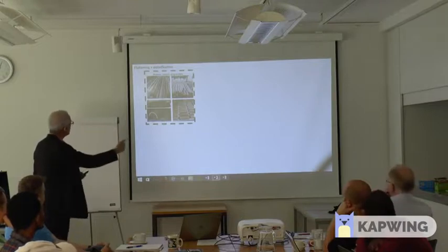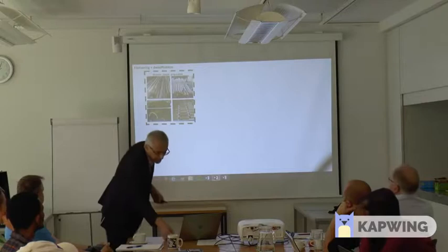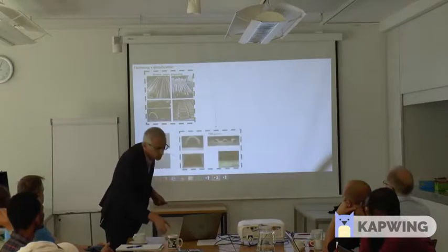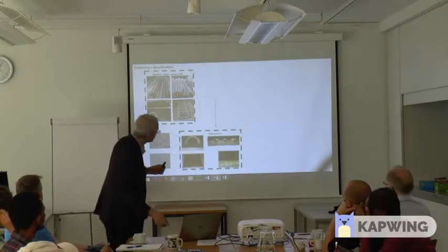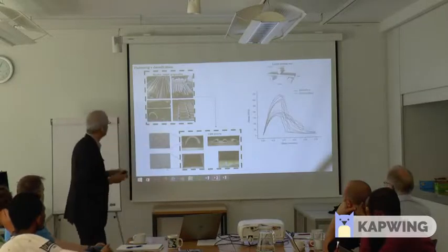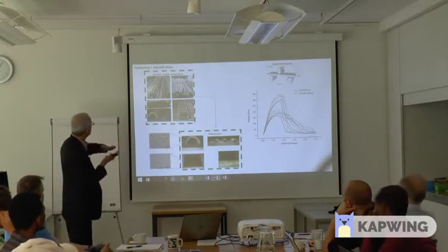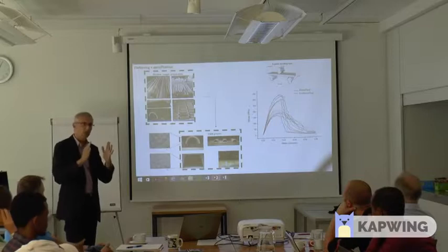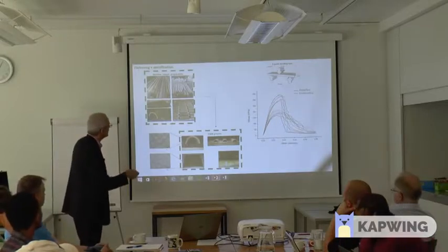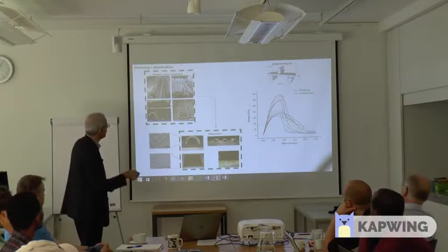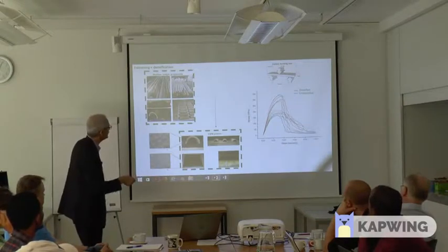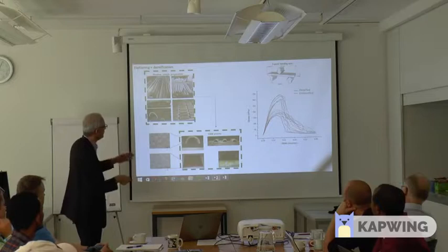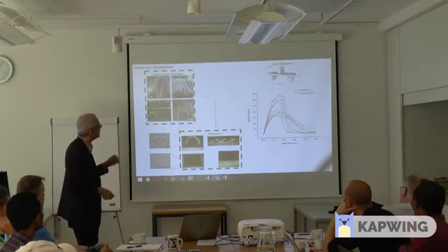And then after that, she's a very hard-working student. She came now to another step, flattening the culms to produce the strips that will be part of the sandwich panels. I mean, the external part of the sandwich panels. So as I showed before, the performance is very nice. We are not just improving the stress, the modulus of elasticity is improving a lot as well because of this pressing.